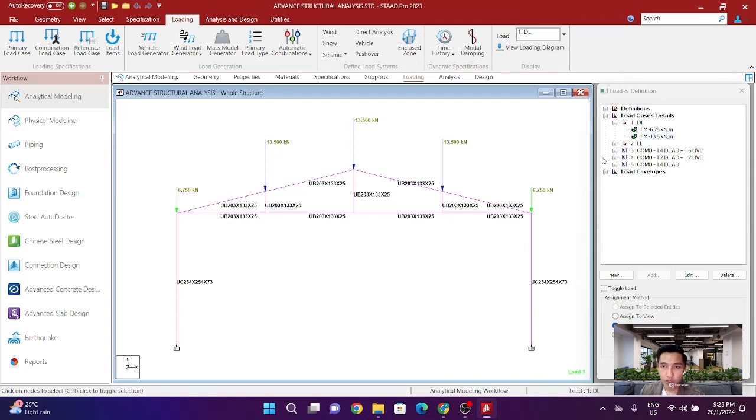This is for dead loads. For the live load, we get 2.6 at the middle, and for the edge of the frames, divided by 2, we get 1.3. For the wind load, we get 2.124. This value is based on the manual calculation of the design.